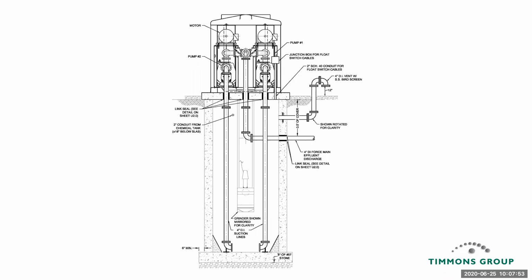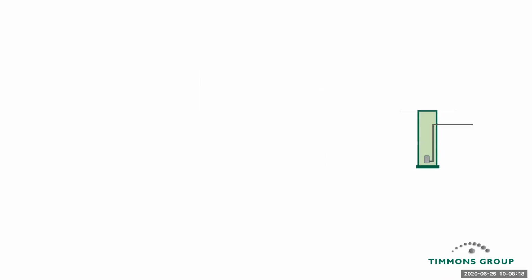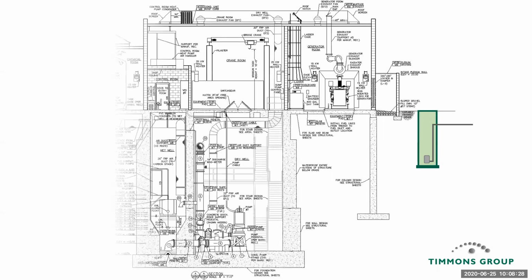For submersible and suction lift stations, the typical size we might see is between 4 feet in diameter up to maybe 12 feet in diameter. Sometimes if we need much more volume, they'll move away from a precast structure and into a custom design. And depths typically range between maybe 10 feet to maybe 20 feet, sometimes a little bit deeper. So that said, what I've got here is a scaled submersible style station with a 4-foot diameter and 15 feet deep to give you a sense for how large some pump stations can get.